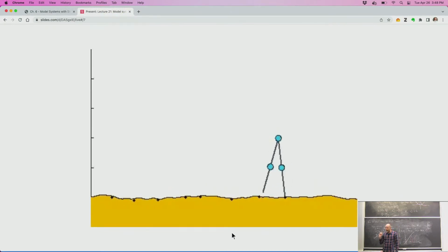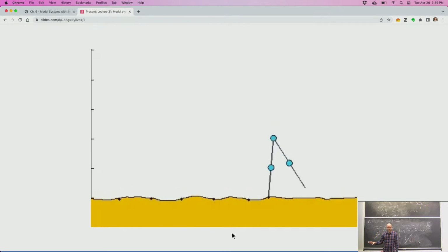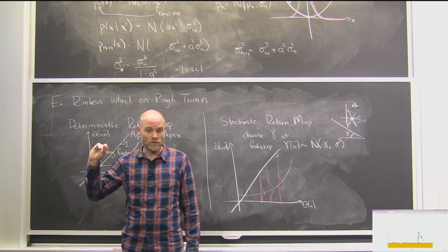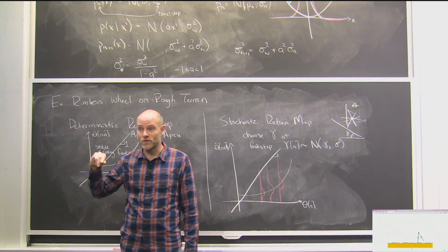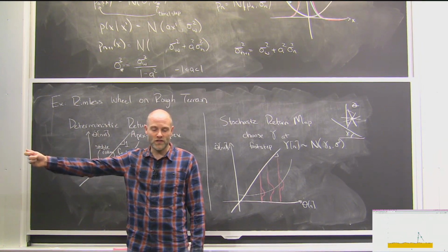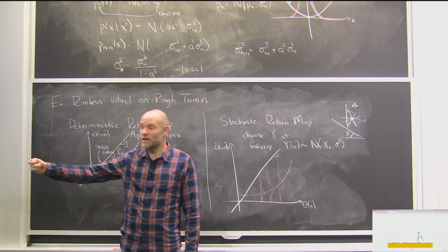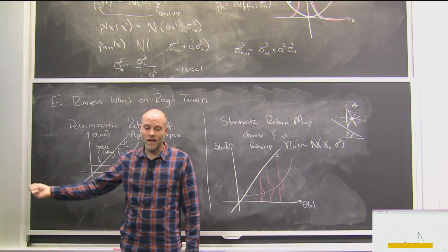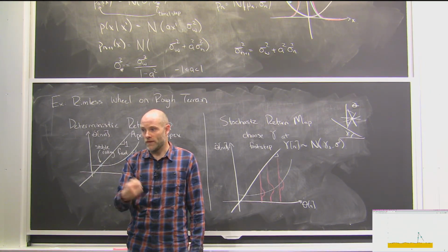Okay, I'll just make one more point here, and we'll really talk about it on Thursday. The modeling that you do for your plant, whether it's a stochastic model or a deterministic model, can change the way you do your control design. So this is just a compass gait now walking over rough terrain, but you notice that the terrain is on average flat. This is a controlled compass gait. This is a small enough system that we could do brute force dynamic programming. If you ask for the optimal deterministic gait controller for this compass gait, and you then apply it to stochastic rough terrain, it does very badly. If you ask for it to, for instance, have the largest mean time to failure possible, and you give it the dynamics of the stochastic terrain to chew on, then you can have a much stronger control design. So those modeling decisions will impact the way you do control, and that's the goal for Thursday.